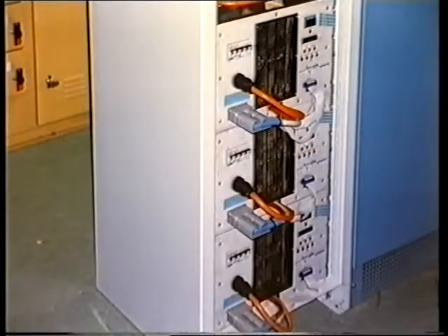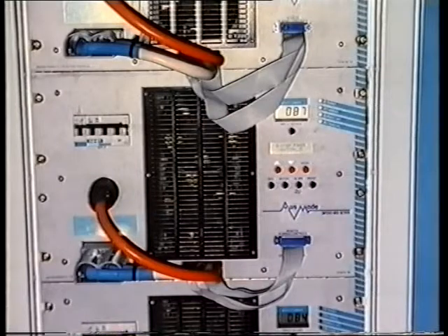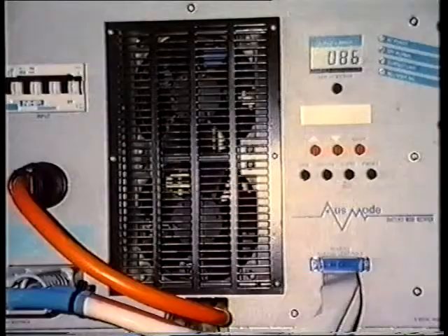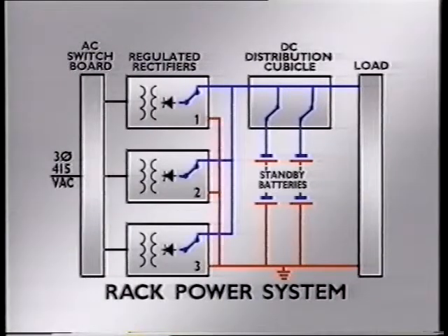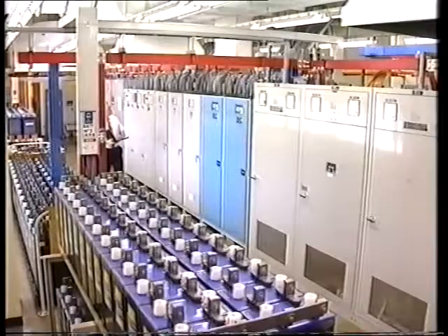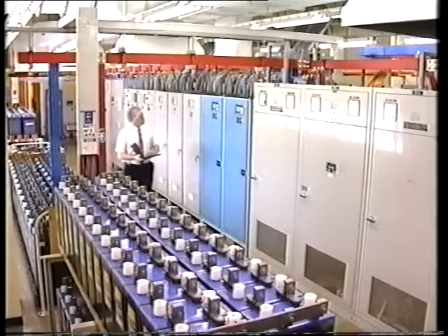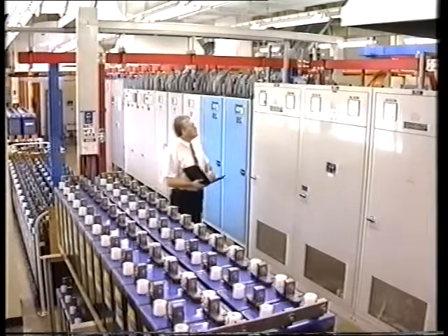There are other online battery power supplies that may be used, for example, using large switch mode rectifiers that are now available. These all have the common feature that the standby battery is connected across the output of the rectifiers and is fully available to the load, independent of the state of the rectifiers. But remember, the buck-boost power supply system is different. Now let's have a closer look.